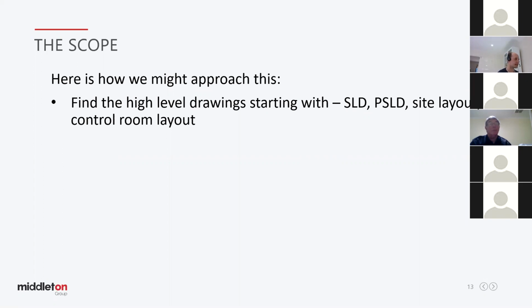So we're looking at replacing two transformers, which means there's a transformer protection panel. There might be X and Y, so each scheme might be in a separate panel. They might be together. There might be a tap changer scheme or something similar that we need to look at as well. There are circuit breaker management schemes, which may or may not be there at this present time. We need to have a look into it. And to do that, we start with the high-level drawings. We look at our site, the conditions of the site. We look at our control room layout, and then it goes from there.